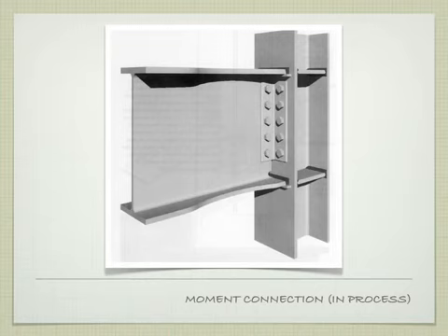Yeah, Tola. I couldn't hear you. The bolts will stay there. So the sacrifice of the 4 or 5 bolts that hold it in place is perfectly fine. They don't add any strength to the moment connection. They would help with the shear connection, just the vertical loading, but nothing to the moment connection because all of the moment connection is handled by those joints, those full penetration welds.